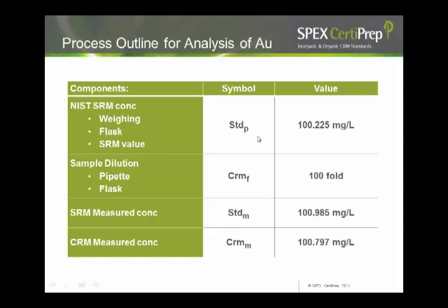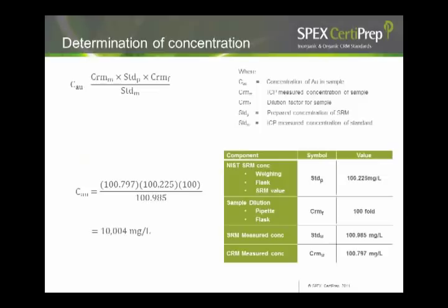Then once you have combined the uncertainty for the overall process, now you have to expand it. Although the combined standard uncertainty is used to express the uncertainty of many measurement results, few regulating bodies require to define an interval around the result. The measure of the uncertainty intended to meet this requirement is termed expanded uncertainty. This is usually done by multiplying by a coverage factor K. Coverage factor depends on the confidence interval and number of observations. K equals 2 for observations greater than 7 at 95%, or K equals 3 at 99% confidence. So finally, you would represent the true value as X equals average plus or minus expanded uncertainty, which is U.